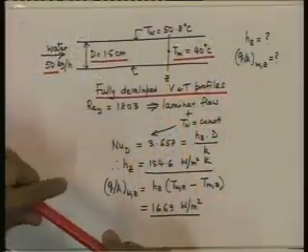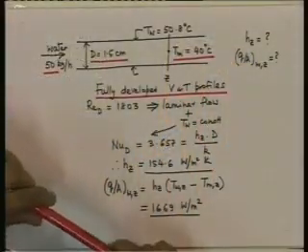Remember that in the thermal entry length, the heat transfer coefficients are higher than in the fully developed situation. Hence, under the assumption of fully developed velocity and temperature profile, we have obtained perhaps the lowest possible heat transfer coefficient in either the first case or the second case.